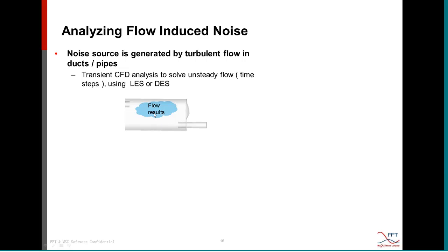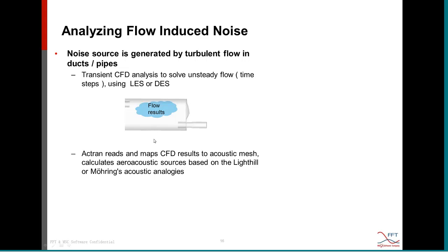Now, to solve this flow-induced noise, we need to go through a two-step analysis. In the first step, a transient CFD analysis will solve the unsteady flow using LES, large eddy simulation, or DES, the detached eddy simulation. And in the second step, the Actran aeroacoustics module will read the CFD result and map it on the acoustic mesh.